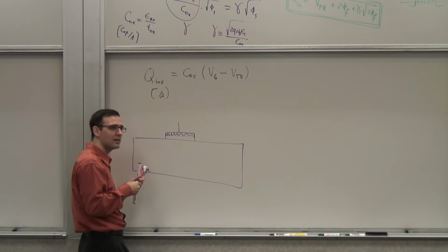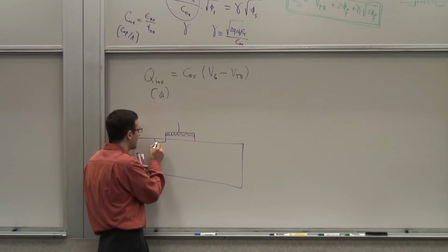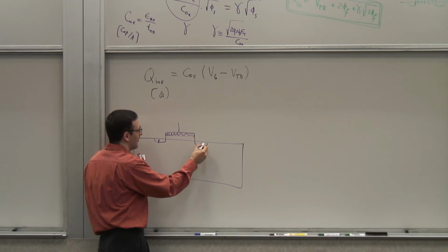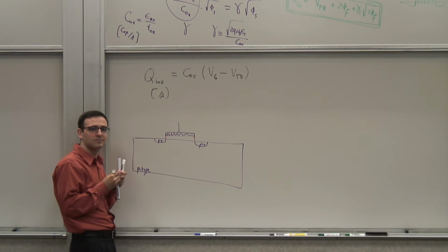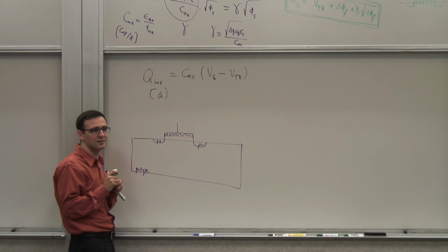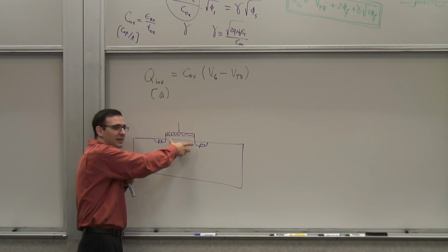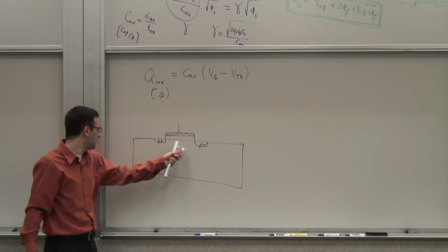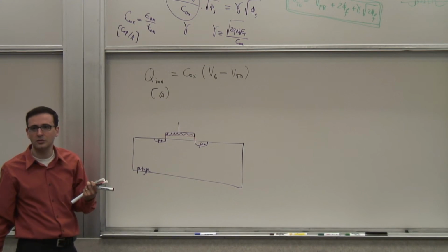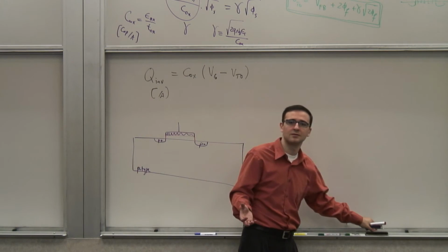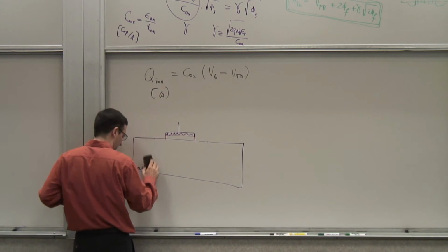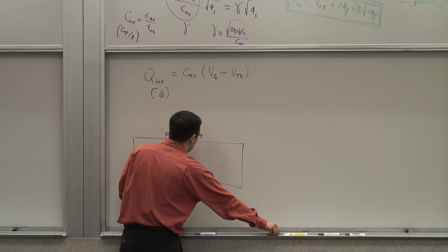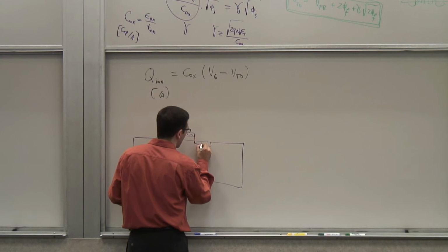Now, can I make a p-type contact? So if I were to make these contacts, let's say here, can I make a p and p, or maybe higher doping level, let's say, to make it low resistance? Can I make it like that? If I make it like that, what happens? Can I turn this transistor off? Or this resistor, can I make this resistor very large? Basically, can I turn the connection between these two off? No, because I have three different kinds of P's, right? There's no way to turn it off. I want something that's normally off. Okay, so if I'm using a p-type substrate, I have to use N plus contacts, and vice versa. So now, instead of this, what I need are two N plus regions.